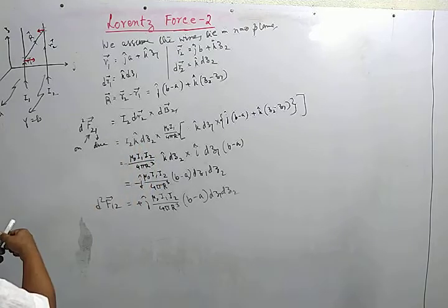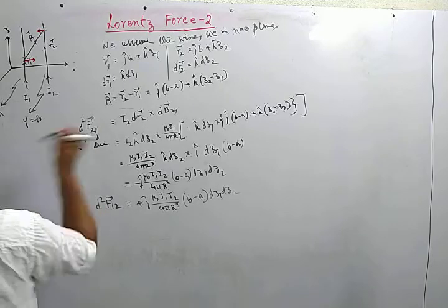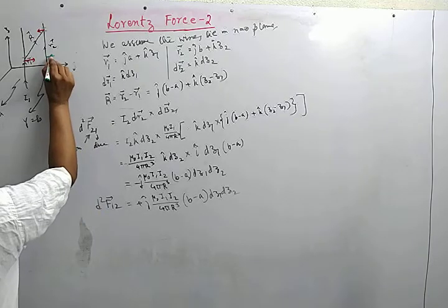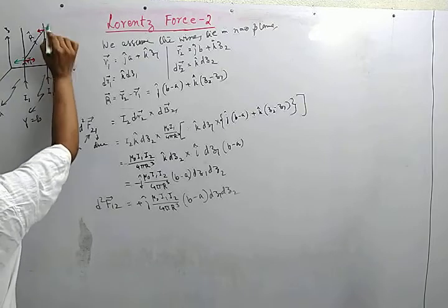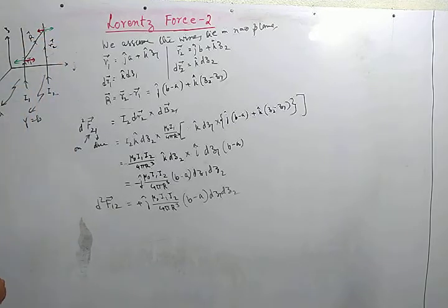If I2 becomes negative, then the force on conductor 2 will be reversed, and so is for this. So there will be a repulsion when the two straight conductors carry current in the opposite sense. Due to the Lorentz force, the conductors are pushed away.